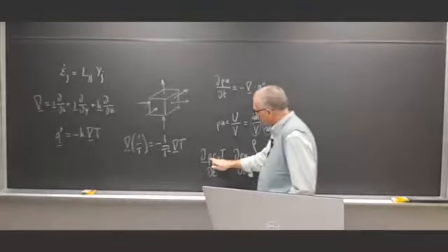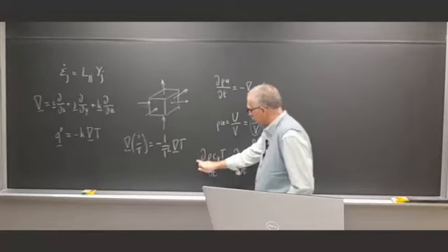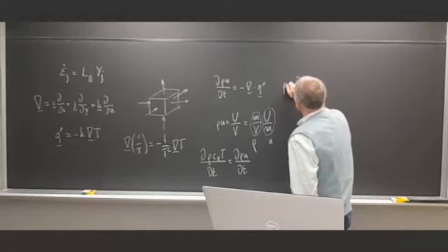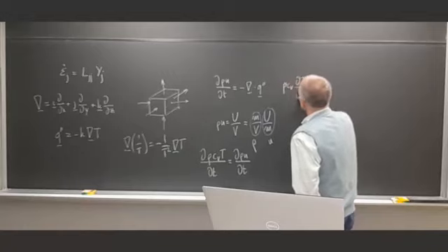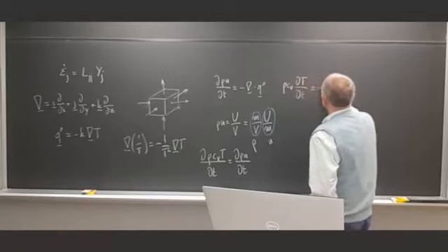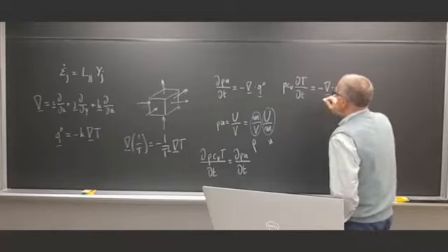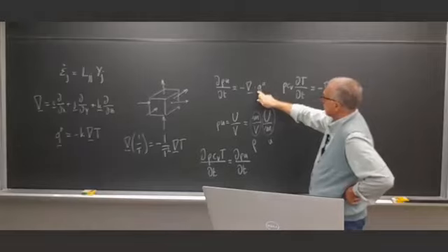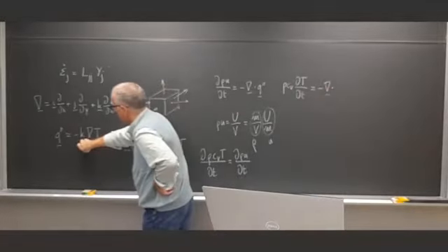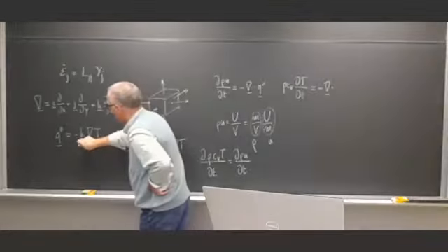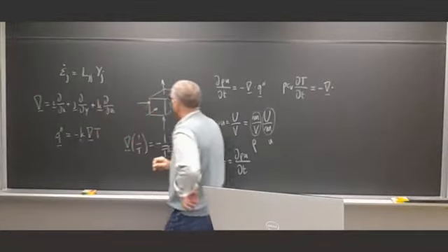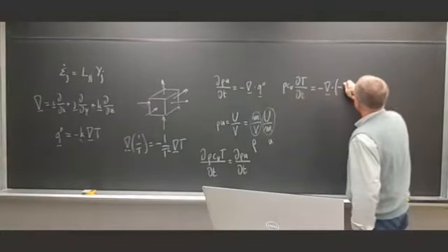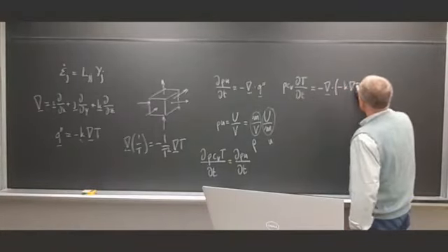And if the density is constant and the specific heat is constant, it goes out of the derivative, and you get only rho Cv dT/dt minus the gradient of Q. Okay, Q is the Fourier equation if you have an isotropic material. Let's keep it isotropic just for simplicity. So I have to substitute here minus K times the gradient of T.